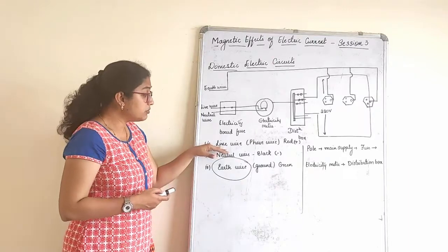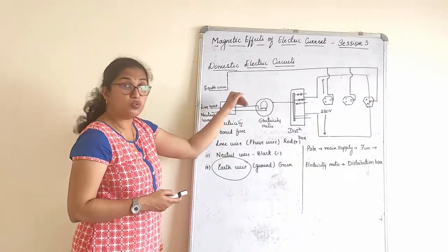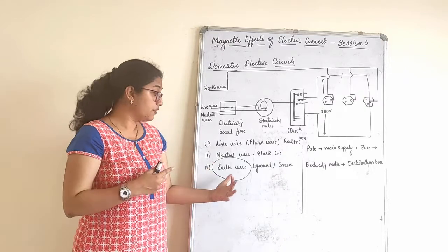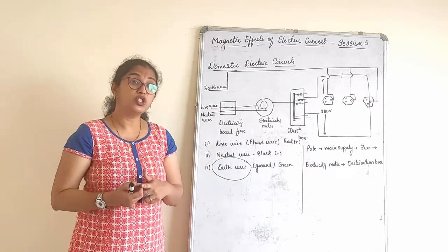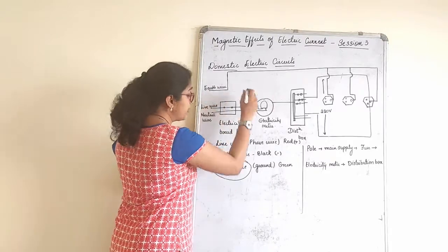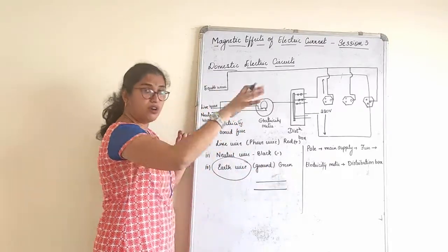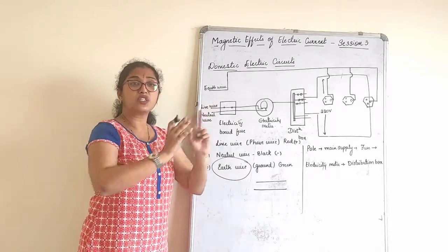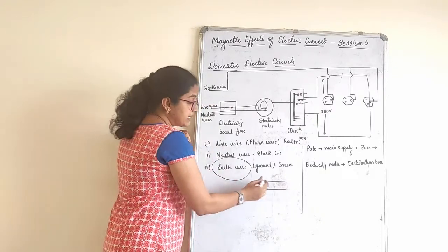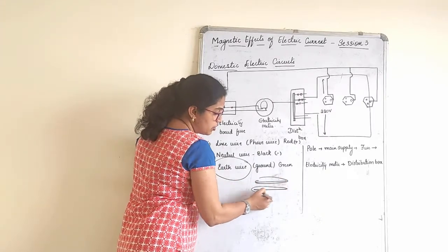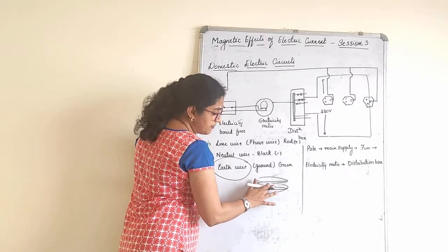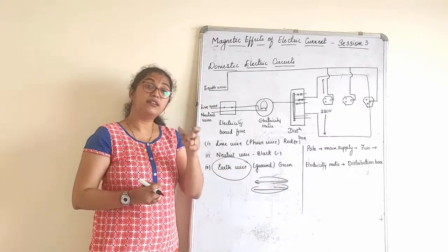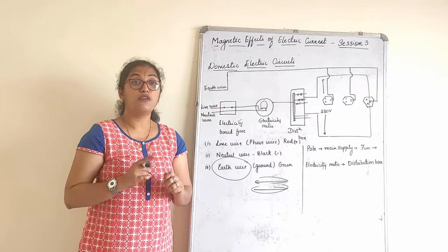Now when these wires are connected to our home, there are chances sometimes of short circuiting, overloading, or earthing not being done properly. Now what is short circuiting? The earth wire and live wire inside all our circuit boards and connections are always going parallel, meaning they are always going together, right? But there is insulation for the wires. By some chance, if the insulation gets worn out and the live wire comes in contact with the neutral wire, there are chances of short circuiting.